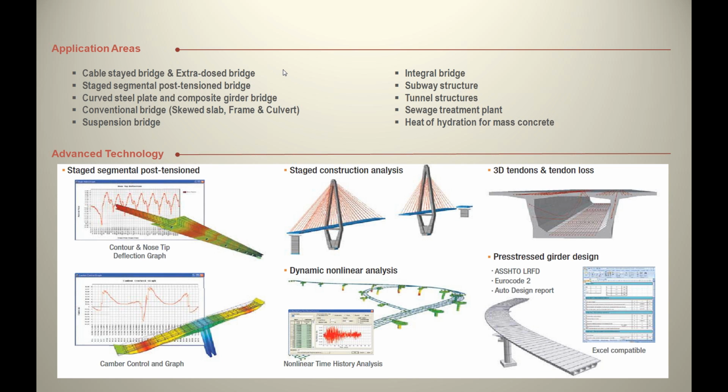Okay. The major application areas for Midas Civil are, as you can see, that Midas Civil can handle almost any kind of bridge, a wide range of bridges. It can handle everything from very simple culverts, RC bridges or PSC bridges to very complex cable-stayed or extradosed segmental bridges, or suspension bridges. It has quite a bit of technology with it: post-tensioning, stage construction analysis, 3D tendons and tendon losses, dynamic nonlinear analysis. So it has quite a bit of variability when it comes to uses.